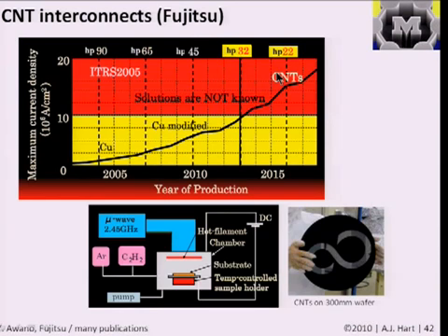circuit element to another. And because when lines of copper get down to this size, say tens of nanometers, they become composed of individual grains, and as you pass current through them, you can basically destroy the material, and therefore that limits their current carrying capacity. And they also dissipate more heat, and that leads to damage to the circuits.